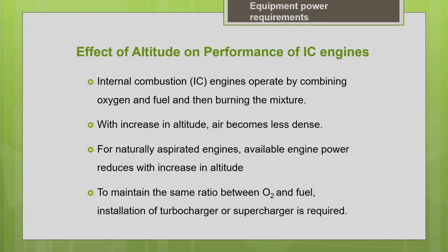We just now discussed how to estimate the usable power. Now let us see what is the effect of altitude on the performance of the engine. As we discussed earlier, the usable power depends upon the underfoot conditions, altitude and the temperature. You know that the horsepower rating of the machine is done at standard conditions by the manufacturer. They might have done the horsepower rating at standard temperature and standard atmospheric pressure. So if your project site is going to have a temperature or atmospheric pressure different from the standard conditions, then obviously the efficiency of your machine is going to be different.